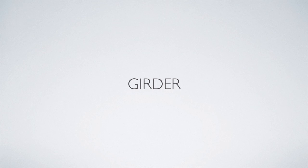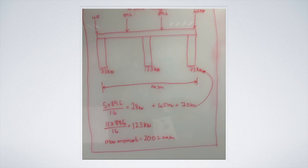So in this section this is how we calculated the girder. For this we used the reaction forces from the beams to the girders. We then found in the course pack a formula to find the maximum moment. This came up with 200.2 kilonewton meters.